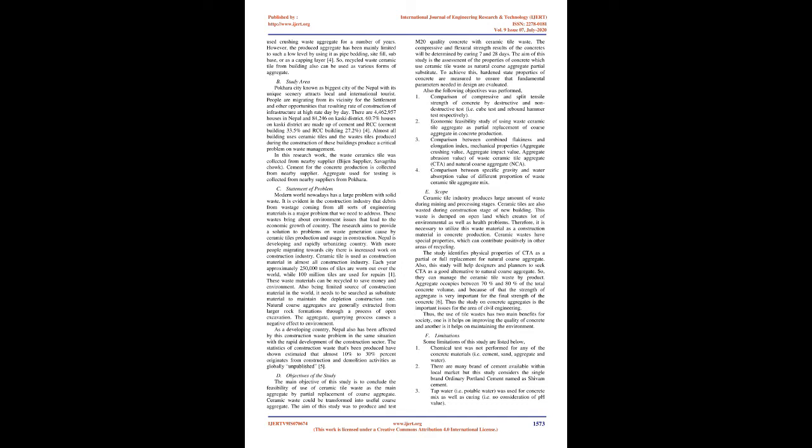A large quantity of wastage is produced annually in all countries. In particular, construction and demolition waste contribute the highest percentage of wastes worldwide, about 75%. Furthermore, ceramic materials contribute the highest percentage of wastes within the construction and demolition wastes, about 54% too. Ceramic waste can be transformed into useful coarse aggregate. The properties of ceramic waste coarse aggregate are well within the range of the values of concrete making aggregates. The properties of ceramic waste coarse aggregate concrete are not significantly different from those of conventional concrete. The use of ceramic waste coarse aggregate concrete has increased because it has various advantages over other cementitious materials.